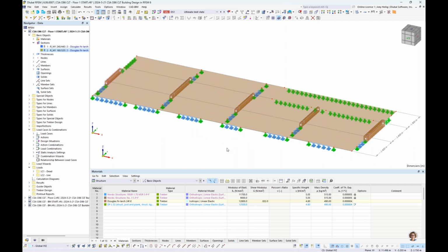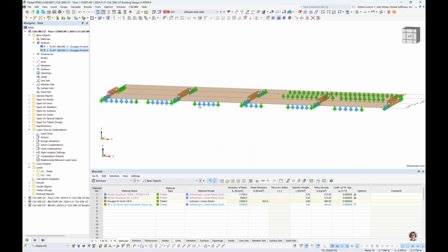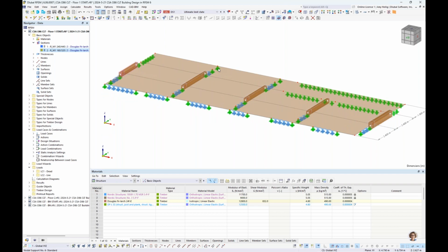You'll also see here several support conditions, and essentially this is a timber floor that is modeled at the elevation 2.75 feet in the vertical direction, or sorry, 2.75 meters in the vertical direction. So these support conditions are going to represent the columns and the wall elements that are framing up underneath it. But because we're only evaluating and analyzing the specific floor for gravity only, we're representing those by the support conditions shown. So for example, we have pin supports here and over on the right that maybe represent the column framing up into the timber floor directly for point supported CLT.